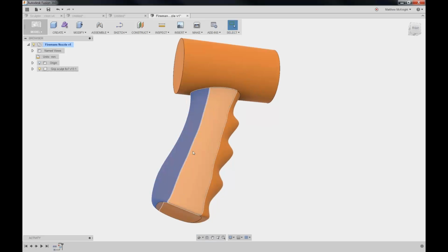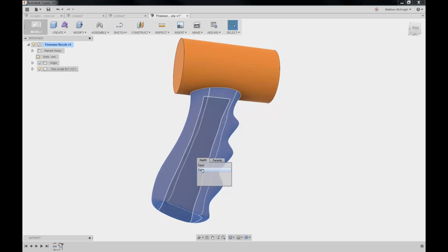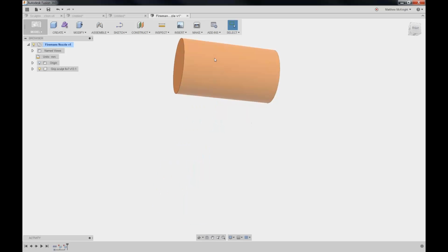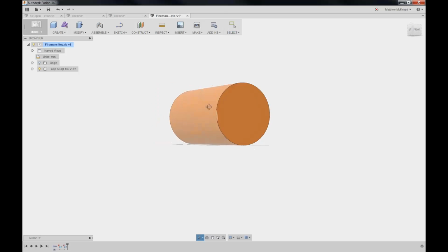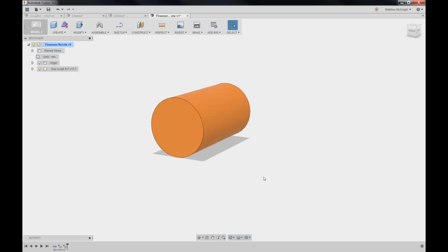Likewise, let's do this for the rest of the handle. So I can select, say, all of these surfaces now to save me going around to the back of the face and choosing the rear face. I can just simply select it using this select other command, and then we'll hit delete, and you'll note that we've quickly and easily deleted the handle and retained is the solid geometry associated with the top of the part.